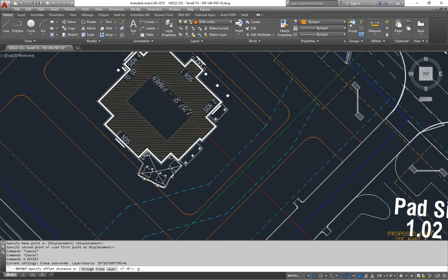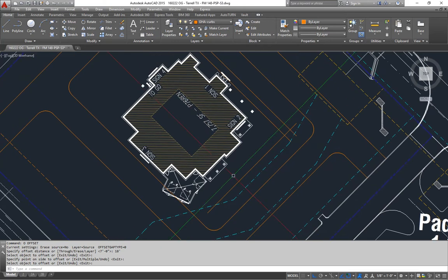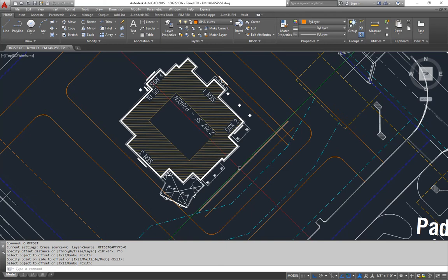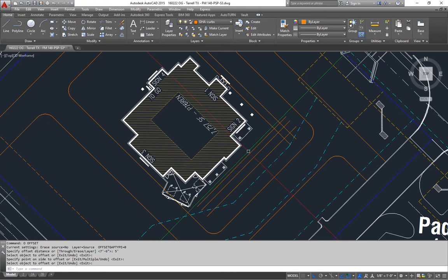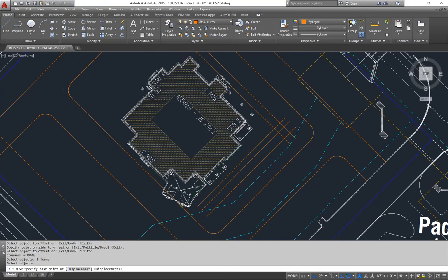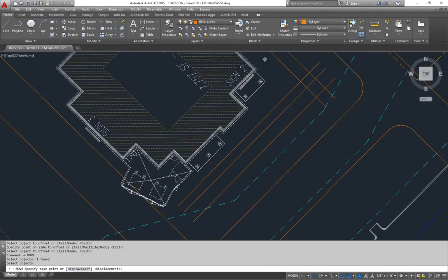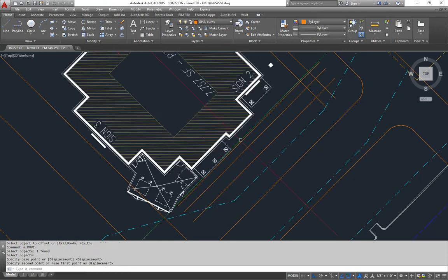We're going to want 18 foot on this side for another row of parking, so we're going to want to get over there anyway. If I had 7'6" for a curb and sidewalk, then we're going to want at least 5 foot additional space there for green space. So I can push this building over a little bit. I'm getting pretty tight down here with the service yard.